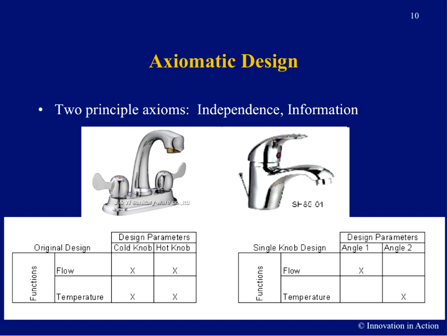Axiomatic design is just one example where you have to have that functional understanding of your problem. Axiomatic design comes out of the work of Nam Suh at MIT, and he wrote a book on his technique, The Principles of Design. But it comes down to two principal axioms. Axiom 1, you want your functions to map independently to your design parameters. And the second one he calls the information axiom, and that simply says the simplest design that satisfies the independence axiom is likely your best design.